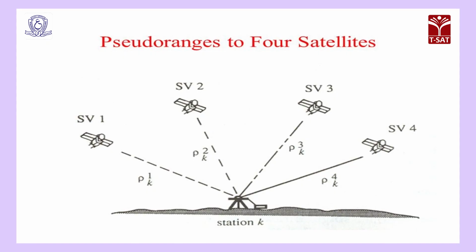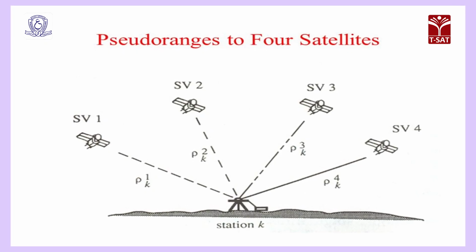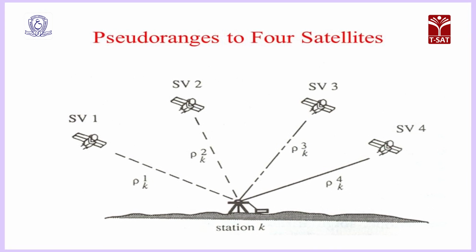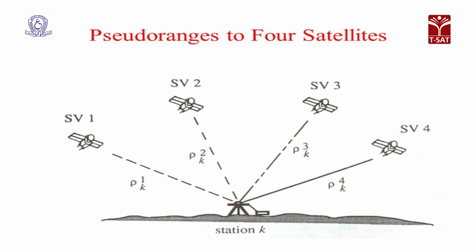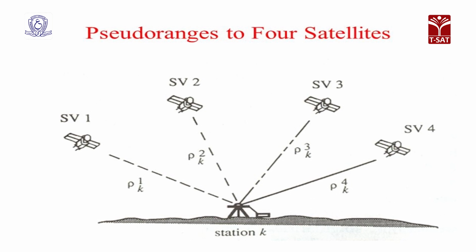with its internal clock, the receiver can calculate how long it took the signal to travel from a satellite to the receiver. The distance derived from this method of computing distance is called a pseudo range, because it is not a direct measure of distance but a measurement based on time. Pseudo range is subject to several error sources, including atmospheric delay and multipath errors, but also due to the initial differences between the GPS receiver and satellite time references.